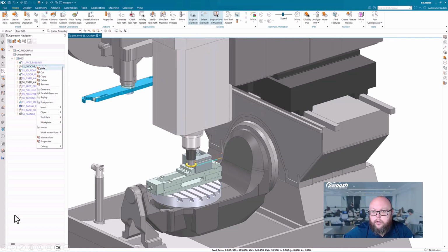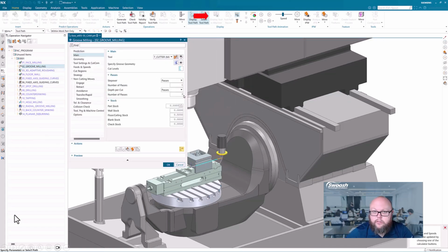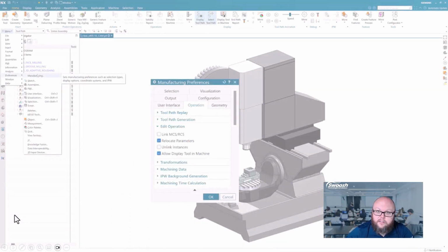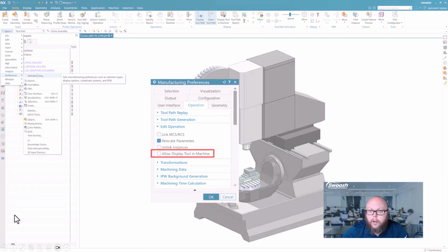So this is really beneficial that we can see right away clearance issues, including things like spindle face, axis motions, all that kind of functionality. So pretty cool new functionality added in to the software. Again, we do have to have that MPP enabled kit, so that's something to talk to whoever develops your posts and sim kits for you about getting that done.